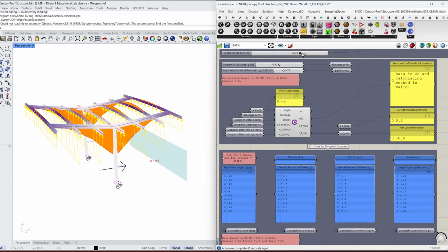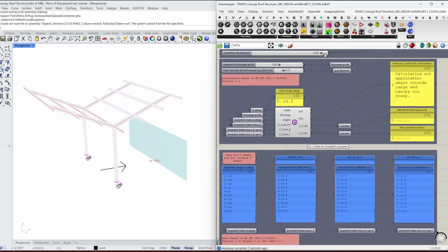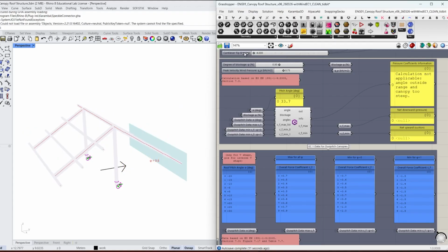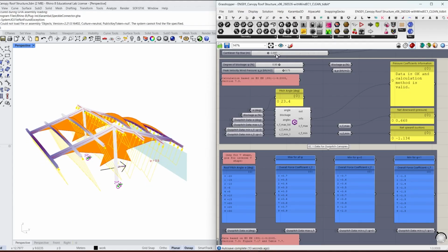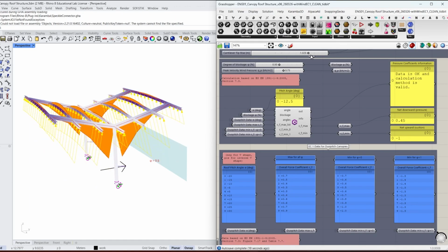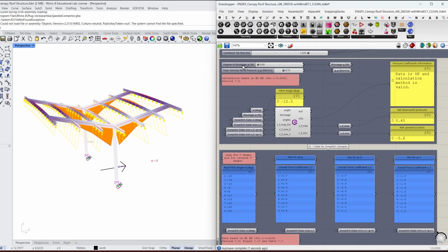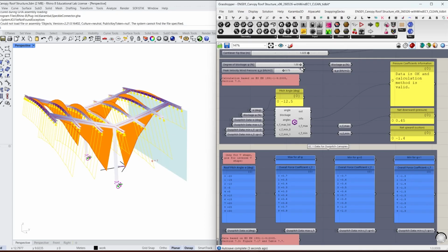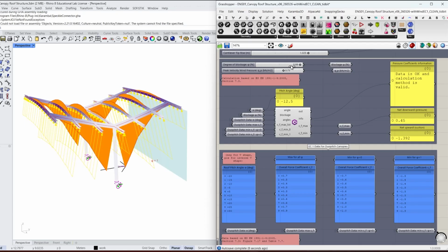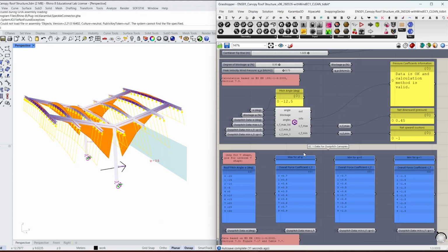Now let's see this in action. We are changing the cantilever tip rise, and for a given span that automatically changes the angle. As we scroll through some values of the tip height change, we can see the angle and the net downward and net upward force coefficients change. We are also schematically visualizing the degree of blockage, and changing this between 0 and 1 is seen to modify the net upward force coefficient, CF_min, but not the net downward coefficient, CF_max. This is behaving as expected.